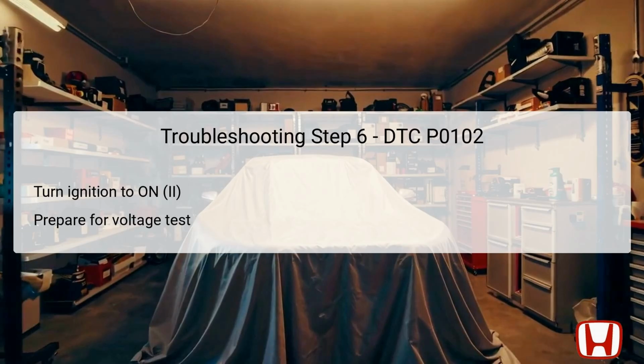the system. This step is crucial as it prepares you to measure the voltage across the MAF IAT sensor terminals accurately. Incorrect voltage readings could lead to misdiagnosis, so it's imperative to ensure the system is prepared for an accurate assessment. Before proceeding, double-check that the vehicle is in a safe condition to avoid any electrical hazards.